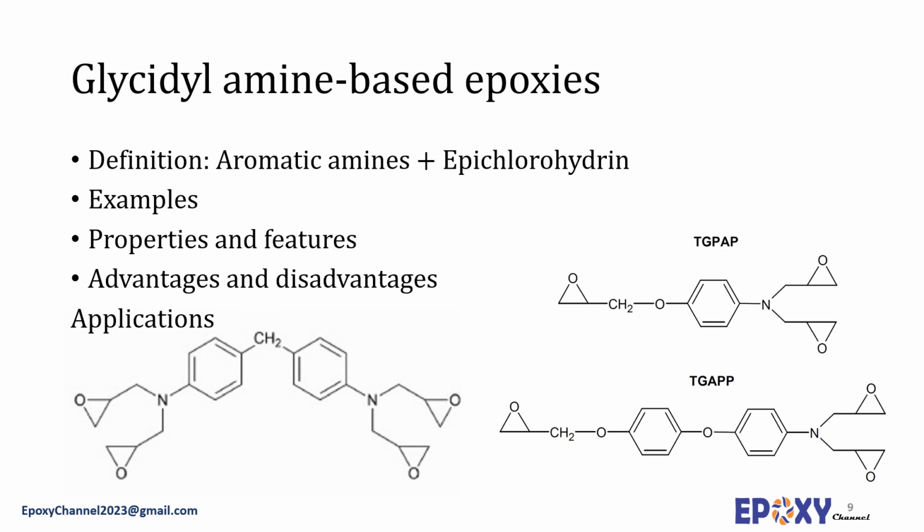engineering thermoplastics. In these resins, a great degree of cross-linkage results in high reactivity, high thermal resistance, high chemical resistance, high Tg, outstanding mechanical properties, and relatively low room temperature viscosity for easy handling. Therefore, these resins are designed for manufacturing high-performance fiber-reinforced composites, adhesives, and coatings.